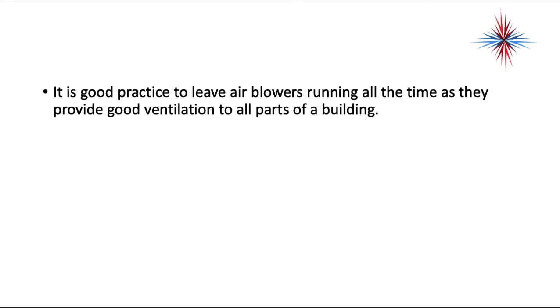It's good practice to leave air blowers running all the time as they provide good ventilation to all parts of a building. This is especially important in commercial buildings. In residential environments, if you have an ECM motor that provides a low flow, just air movement, and if you have very well insulated ductwork, especially in an attic, you have to have really well insulated ductwork to be able to do this, or you start pulling in a lot of heat from the attics.